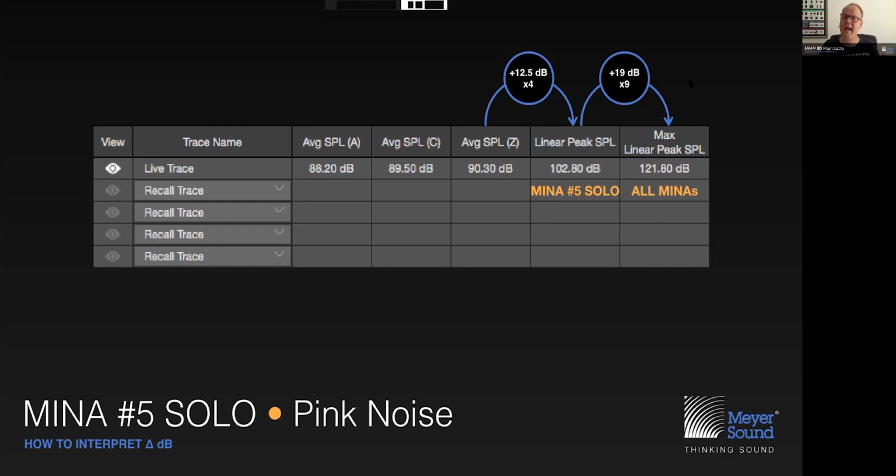But that has to do with the fact that where that microphone is living, you're not equidistant to every enclosure in the array. And that means that even though time and therefore phase might be discarded, you still have your inverse square law, your attenuation loss over distance. You still have that introducing minute level differences, because the loudspeakers that live at the edges of the array had to travel a longer distance to that same microphone, and therefore are attenuated slightly more with respect to loudspeaker 5 from the top, that is staring directly into the microphone membrane of our measurement microphone. So we have minute level differences.